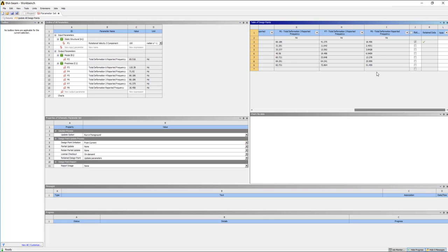If we come all the way down to the first frequency, you can see it was around 1.7 hertz when it was unprestressed. Now, going from 100 RPM at around 2.5 hertz, it rises all the way up at 3,200 RPM. So you can see the differences it gets.